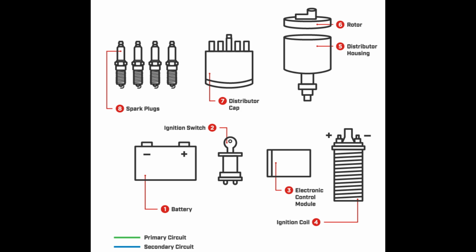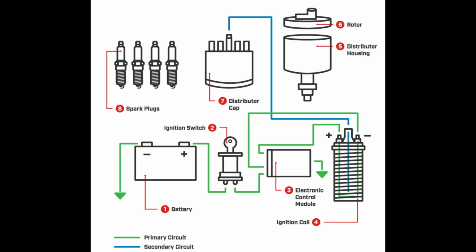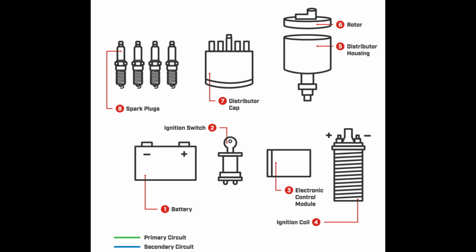Ignition coil construction. In earlier times, ignition coils were made with paper-insulated high-voltage windings and varnish, fixed into a steel can which was filled with oil for insulation and water protection. In modern automobiles, coils are cast in epoxy resin, which fills any air gap in the winding.